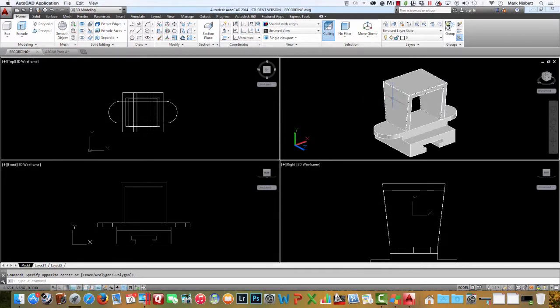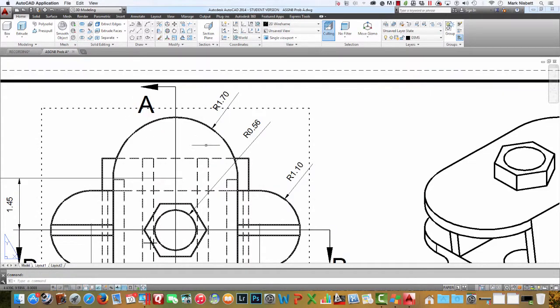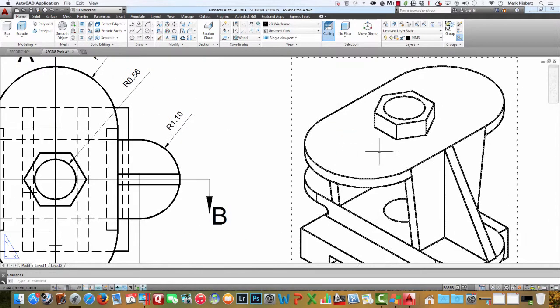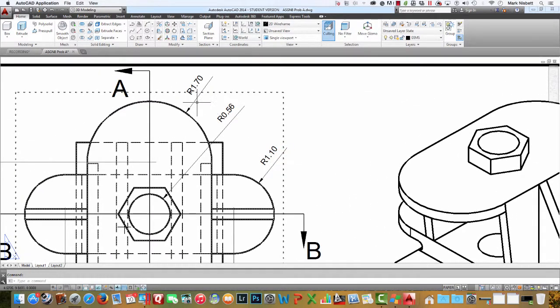So next up on the agenda is we need to put the top on this. We can see we have still two solids. We don't have to join everything together at this point, but our next thing that we're going to tackle is going to be this upper portion here. If we look at that, you can see it basically has an arc that comes out here, and the arc itself is 1.7 the radius, so that's half.